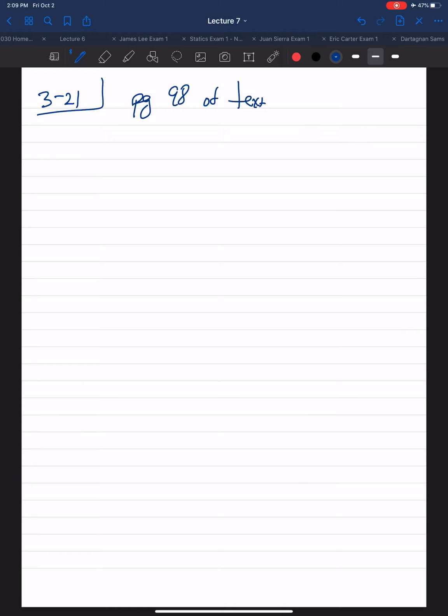So we're saying we need to produce a clockwise moment of 500 pounds force inch. So we know clockwise, we need a moment of, we'll say, with counterclockwise being positive, negative 500 pound force inches, because clockwise means negative. So force F has an angle here. I'll try to draw it out. The angle being 30 degrees.